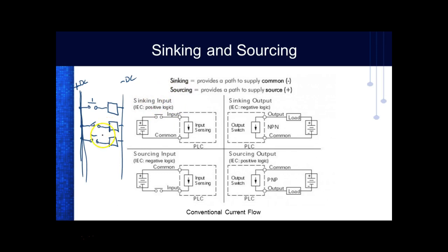We're dealing with sinking inputs. So this would be one of the inputs on my PLC, like input 0/1, this might be input 0/2, and this might be input 0/3. Now what's the common for all my inputs? Positive. What's the common for my PLC? Minus.